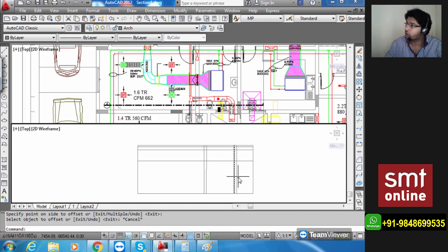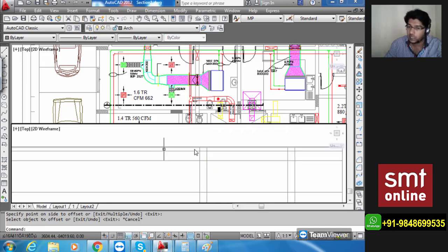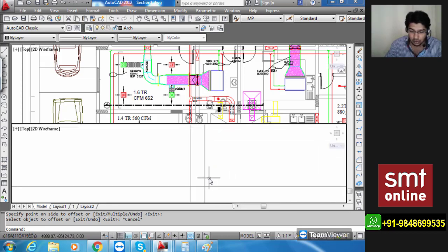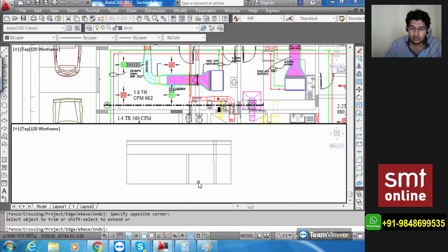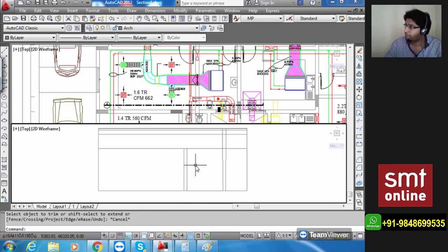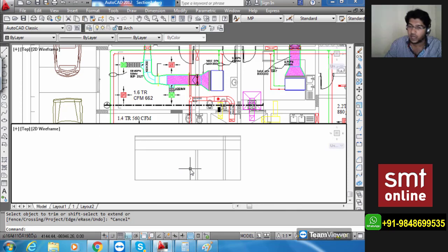My structure is all over the building, so that is going to be applicable all over the design, but the wall is not going to enter inside the false ceiling or the slab, etc. So you have to use TR double enter, trim it from the false ceiling area, and it is only and only available inside your conditioned space. Fine. So now, because this is a wall, this is a column, and we don't want to just name them, we can do the purpose of hatching.